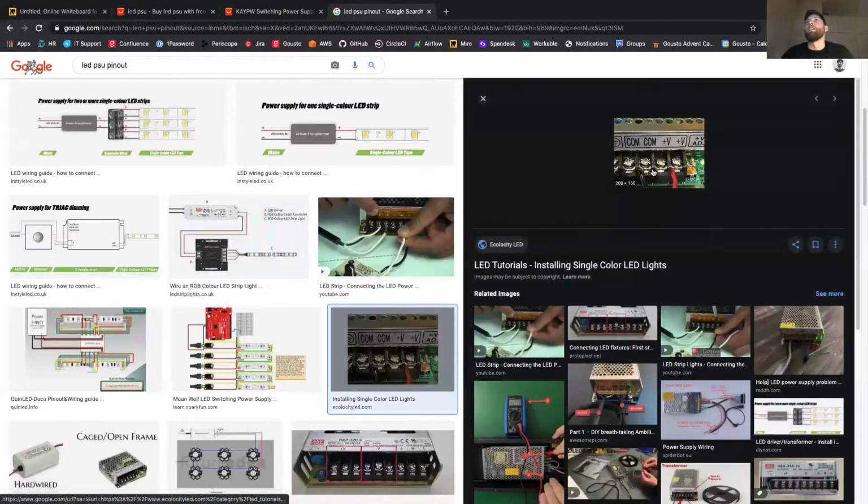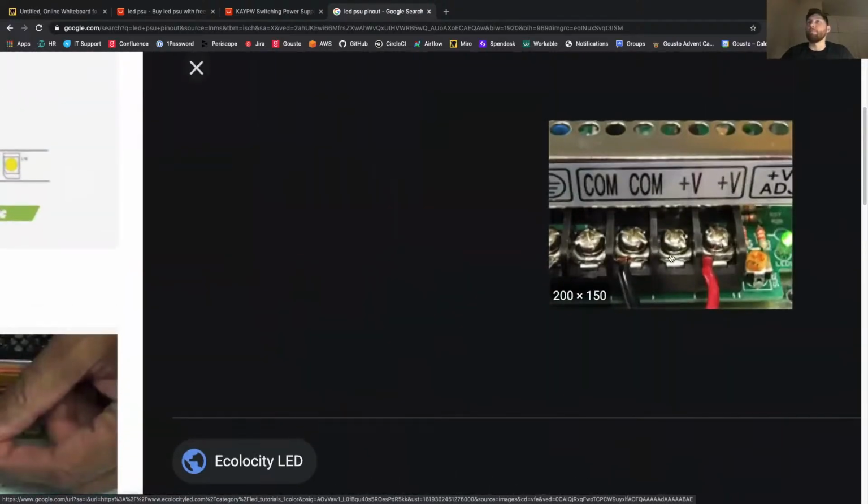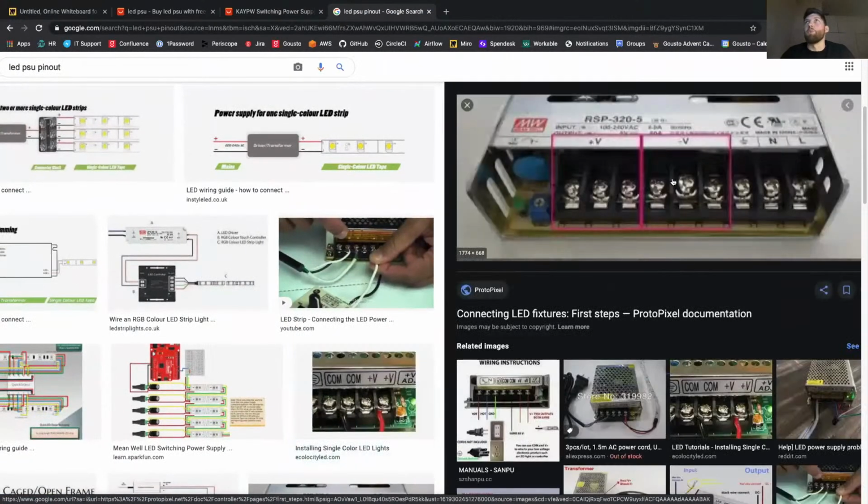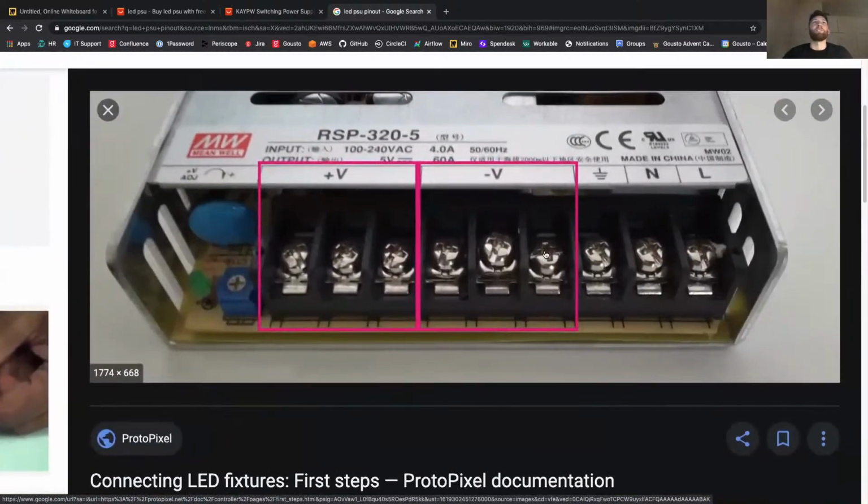So this is what you'll typically see when you buy one of these units, okay? So right here, you have your mains input. This will be taking AC current, AC power from your main socket or your generator. Okay, this is your neutral line, this is your live line, and this is your earth. We can explain the difference between those in a little bit. So that's how power gets in to this transformer.